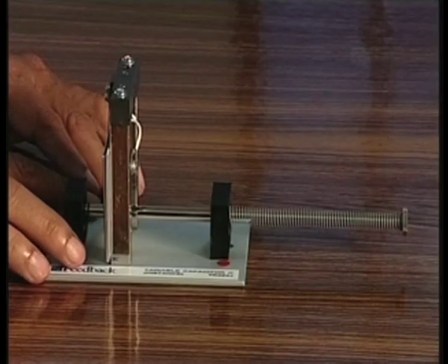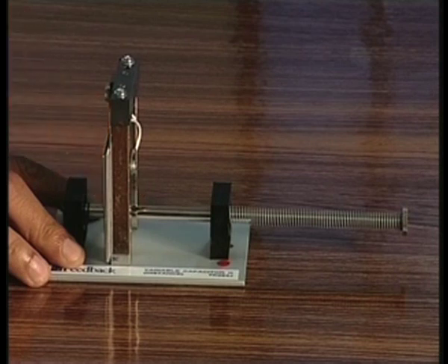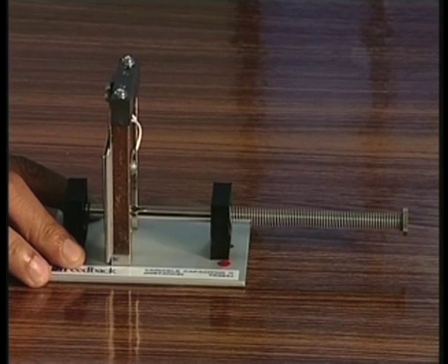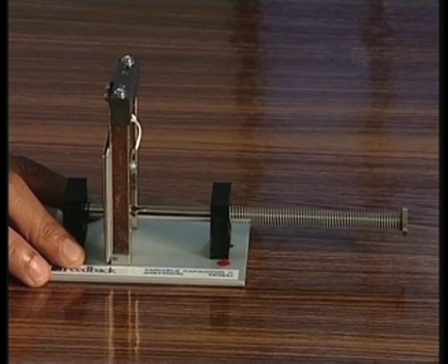This is another application of the capacitance sensor which can be utilized to measure displacement. Usually capacitance sensors are based on three different criteria. One, you can vary the area of the plates; you can vary the displacement between the plates, that means the separation of the plates; and also you can vary the position of the dielectric medium inside the capacitor. The particular gauge which you are looking at now depends on the displacement.